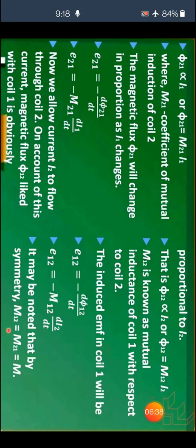The magnetic flux phi 21 will change in proportion as I1 changes, that is E21 is equal to minus d phi 21 upon dt. Then we get the equation E21 is equal to minus M21, putting in the value of phi, into dI1 upon dt.